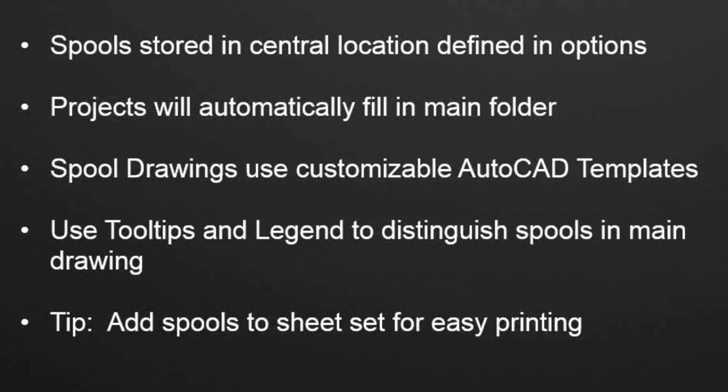So ideally you're going to want to have the spool number and the part number in there, and then the manufacturer information for the pipe fittings, and then your pipe length for pipe. And again, we offer some spool templates in our out-of-the-box setup, but they are completely 100% customizable to anything that you want.